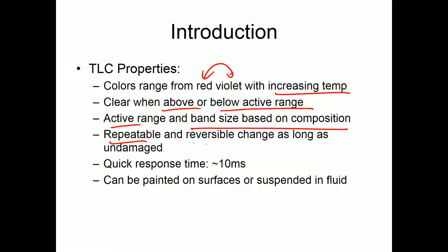It is repeatable and reversible as long as it is undamaged. That means once you take the temperature out, the color will return back to its normal. So, you can use it again and again. It is not a one time use and throw kind of thing. It has got a quick response time of the order of 10 milliseconds, which makes it a very attractive proposition for certain experiments, not for all, because 10 milliseconds still is a very high time if you are dealing with very turbulent flows and things like that. But for many applications 10 milliseconds can actually be a good thing.